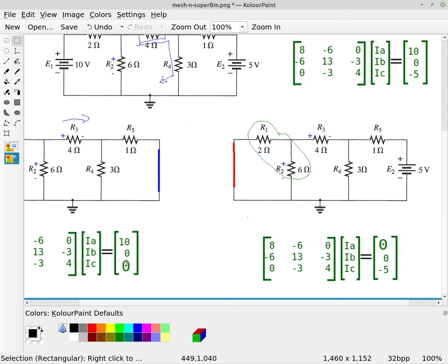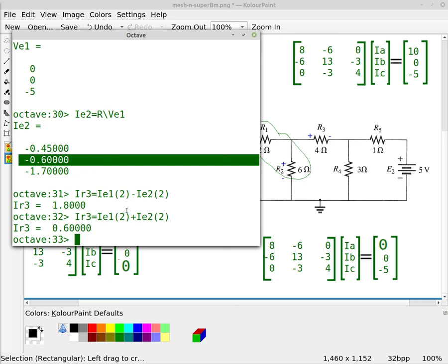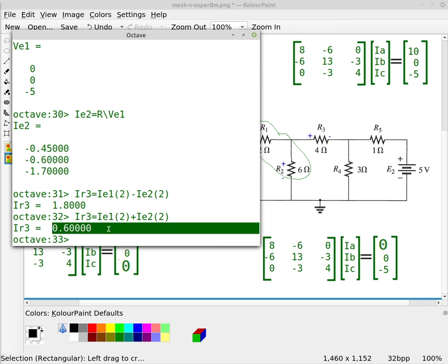But set all other voltage sources to 0 and solve for that one voltage source. Then you algebraically just add those currents together, right? That's a plus sign there. If they're negative, then you're effectively subtracting them, and you're getting your final result. All right, so that is superposition.